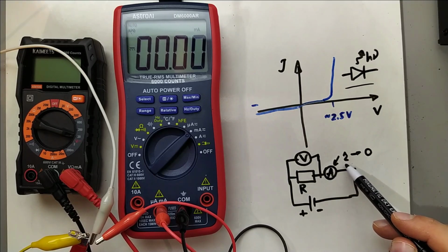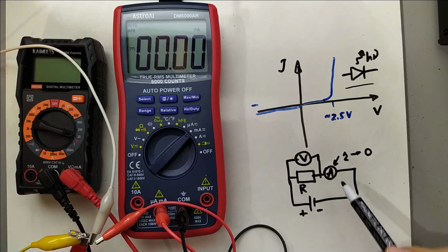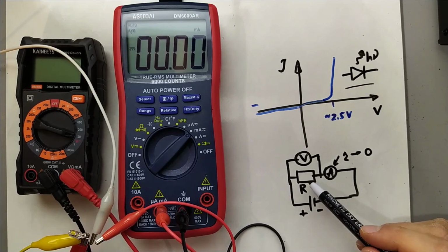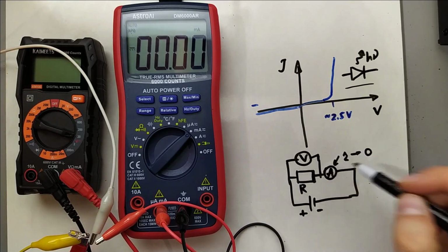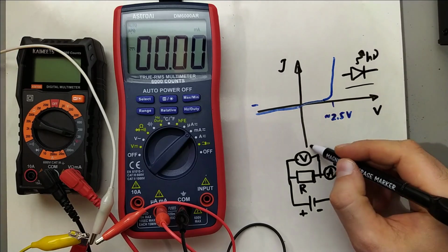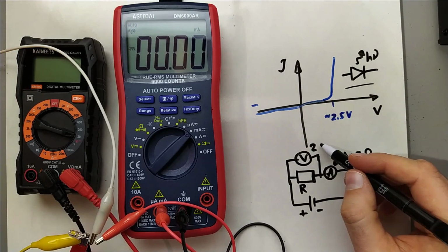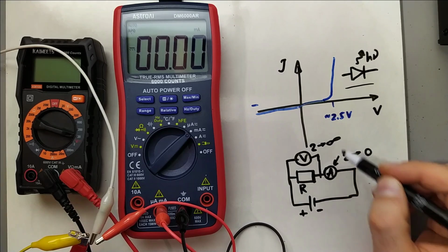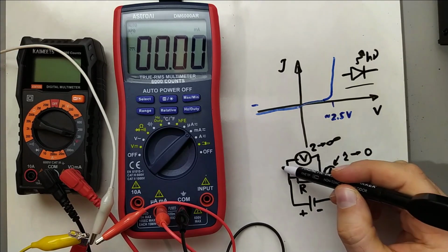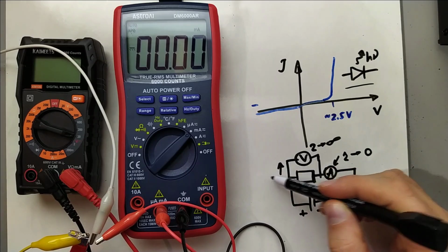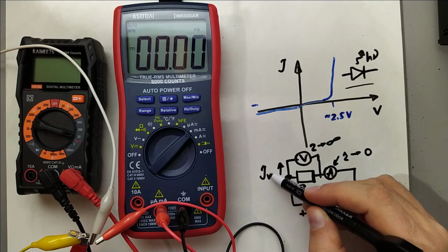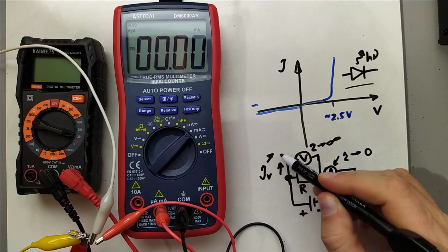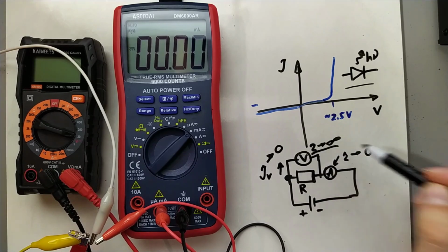So it should not limit current through this electric circuit, should not add any parasitic resistance to the resistor under investigation. At the same time, internal resistance of voltmeter should approach infinity. So we need to be sure that at this junction current which goes to voltmeter is approaching 0. For that purpose, internal resistance of voltmeter should approach infinity.